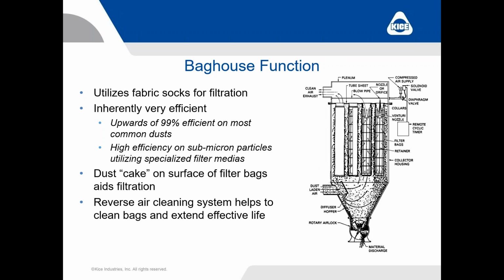So with that being said, it's difficult a lot of times to just open up the access door in a baghouse and use your eyes to see how dirty a set of bags are. A lot of our processes, the dust may be light colored anyway, so it's hard to gauge how dirty they are. But if you take your finger and flick a bag and you get a little bit of dust that comes off of it, that may not necessarily mean that's a dirty or plugged bag. We actually want at least a small amount of dust cake or surface buildup in order to effectively filter that air.